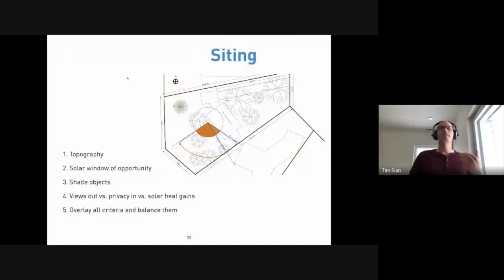Let's get into some of the design things that are super important. Siting, especially single-family homes, they require passive solar heat gain to meet the standard, and they really feed off of it very, very well. This is the site in St. Paul, by the way, that Eric, that you came and visited. This was done many moons ago before we even had the design for the building. But understanding where is the sun, where are the views, where is the shade, all those things are super important. So we try to study that hard up front.